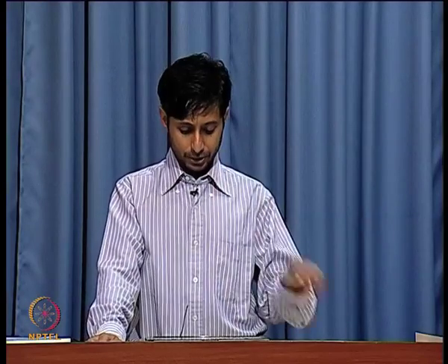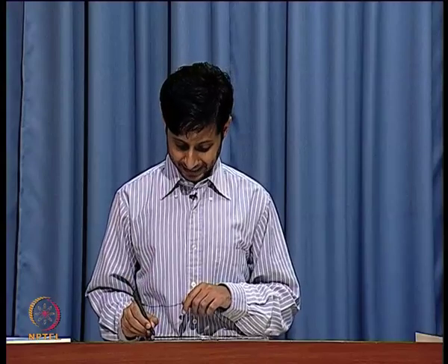So, in that case, you can't isolate the gate from the channel, right. Now, this gate resistance that I have noted down over here does not account for that. This is something else. This is even if the gate is perfect, just the charge traveling all over the gate and reaching all the different points, the charge has to go through resistors. So, that is what this RG is trying to account for.